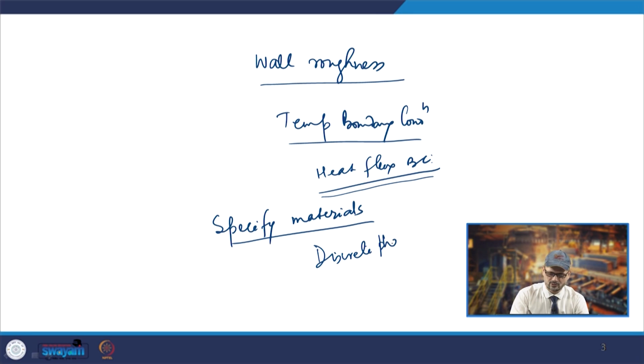So, they will be moving in that domain accordingly, and they will be floating or they may be going to the walls, where, as we had discussed, you will have the condition at the wall, like it may be sticking or it may be reflecting there. So these conditions need to be specified. These are also boundary conditions for these particles which are required to be provided in the case of the discrete phase.